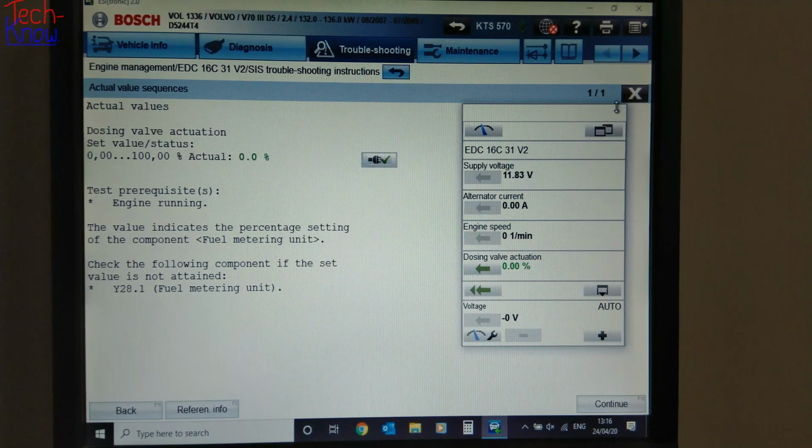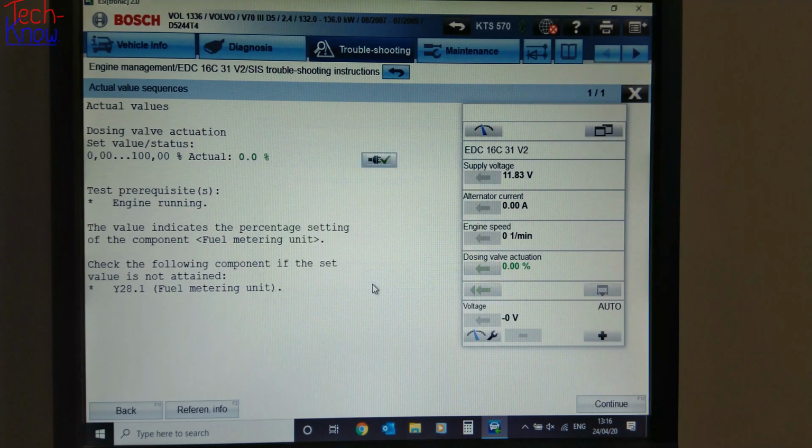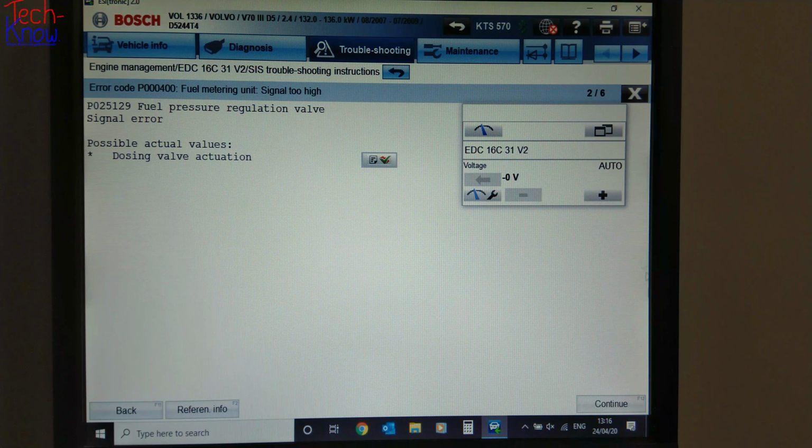So that's quite a nice little extra that you've got there, being able to bring up this information of what's actually going on alongside the technical information for you. If I click continue, I just get a confirmation again that I've read that section and worked through that section. As you see here, bits of this close back down because there's no live data values shown over here, so it shuts them down, but the bit that is left going is the multimeter if I so wish.